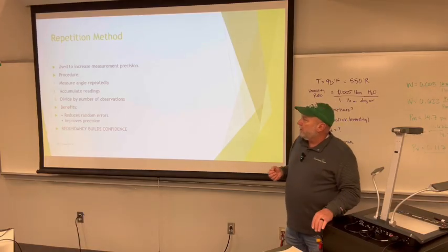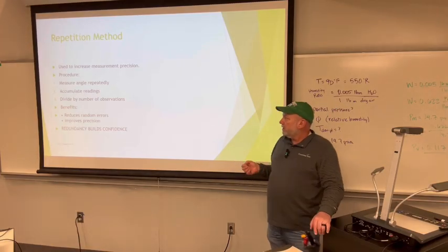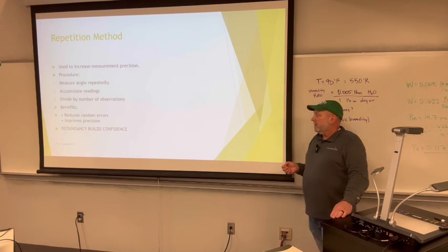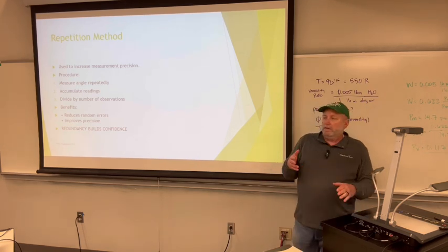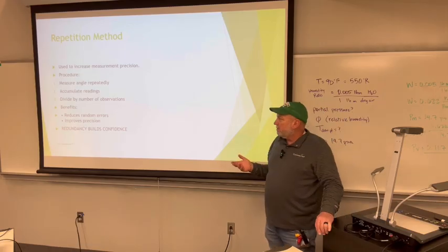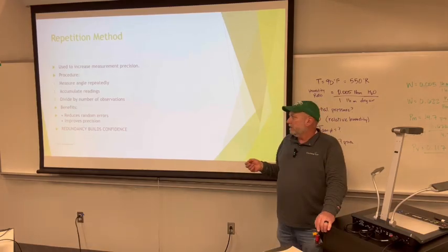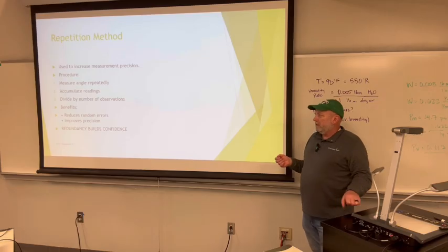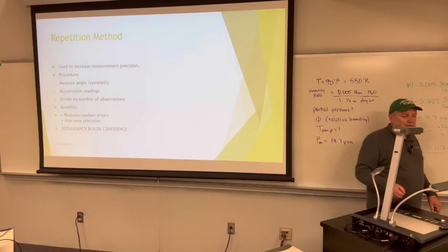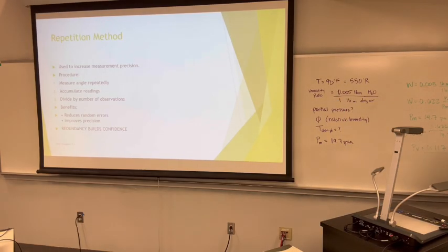Measuring angles repeatedly, you accumulate the readings and divide by the number of observations. So this reduces random errors and improves precision. And there's also, I like to say, redundancy builds confidence. We like that repeatability.